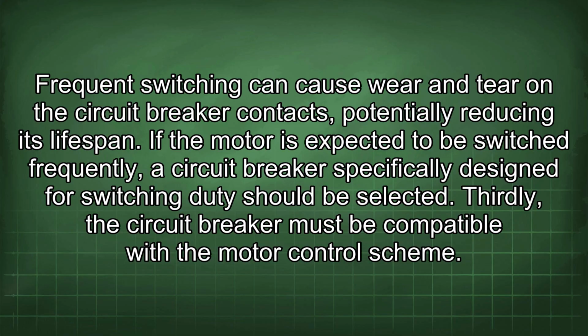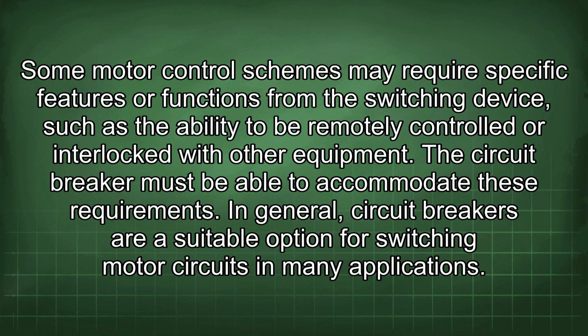Thirdly, the circuit breaker must be compatible with the motor control scheme. Some motor control schemes may require specific features or functions from the switching device, such as the ability to be remotely controlled or interlocked with other equipment. The circuit breaker must be able to accommodate these requirements.